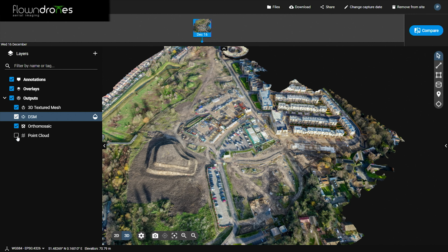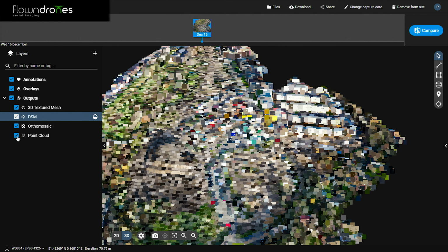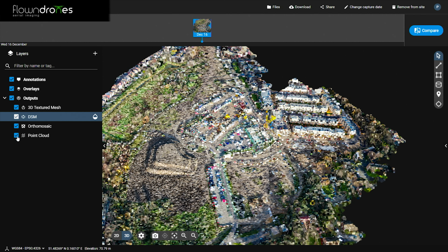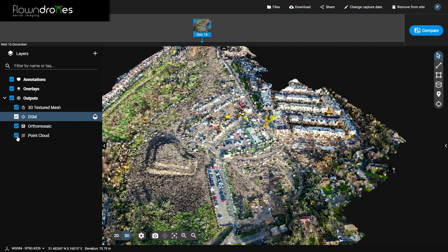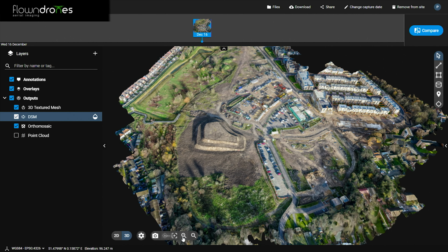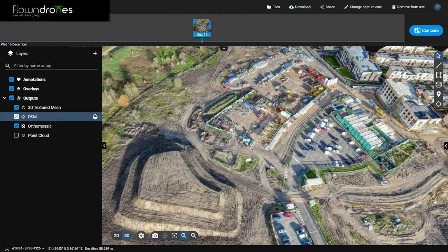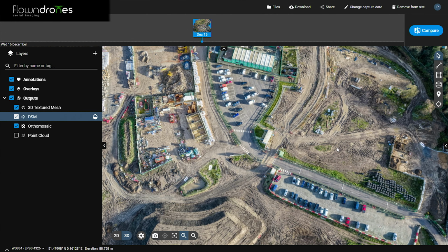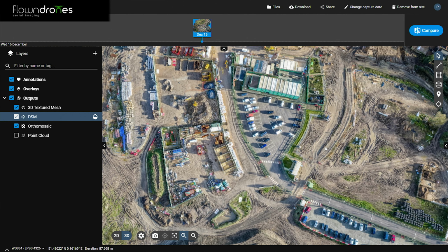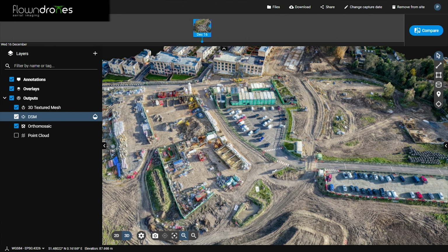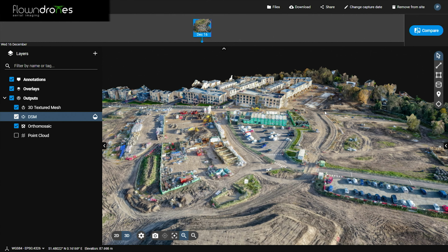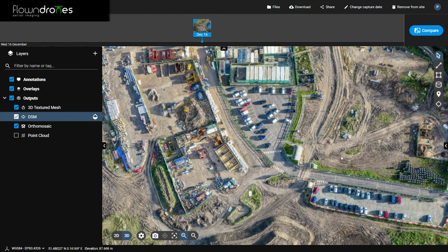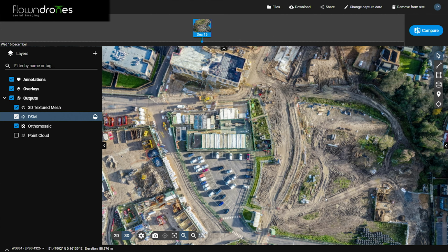Also able to create point clouds, which are more involved. They take the computer a little bit longer to render, and then you can zoom in on these and have a good look around. They're more accurate from straight above. If you want more accuracy lower down, the drone can be flown at lower heights, but these particular ones are made from 400 and 300 feet.